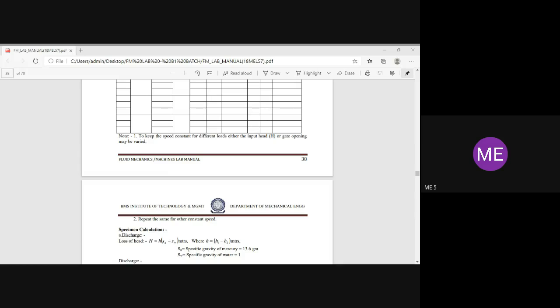Okay, now I shared the constant speed operation. Sometimes they make the speed 1000 RPM or 800 RPM; depending upon this, you have to calculate. Here the speed of the Pelton turbine is kept as 900 RPM. For 270-degree gate opening, I am sharing the details. Pressure is 1.6 for the first trial, N is 900 RPM, head over the notch 0.5, F2 minus F1 is 0.7. Next, second trial pressure is 1.8.